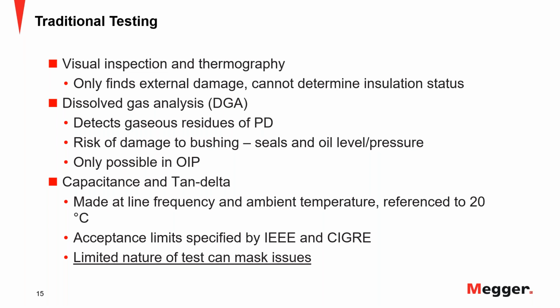And actually, it's very interesting the way that you determine the temperature of the bushing, because there's no sensor. As I mentioned before, there is no thermal sensor to tell you what the insulation temperature on that bushing is. And when you start looking into this, how will you determine this temperature? So some of the recommendations given in different literature is talking about taking, for example, an average between the top oil temperature of your transformer and the ambient temperature, and make an average of those two numbers. That is one approach.